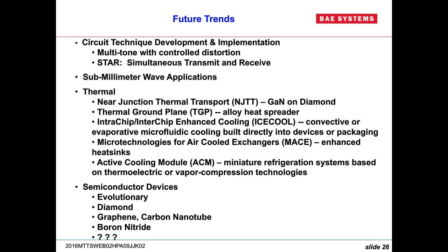Graphene and carbon nanotube have theoretically shown some promise, but there's significant problems. In particular with purity, there still is a tendency of carbon black structures to find their way into built materials. And you can't have that happen in a semiconductor. There are massive defects that don't allow you to build a large periphery semiconductor.